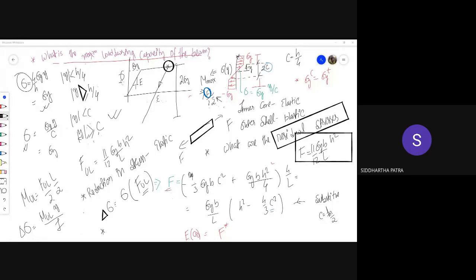Now the second part of the stress distribution, the stress distribution of the second condition where the material doesn't go into plastic deformation, that actually you need to think of is happening in reverse, as in unloading, and that you'll have to subtract from the current stress state to get the residual stresses.